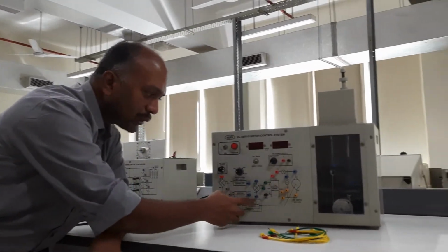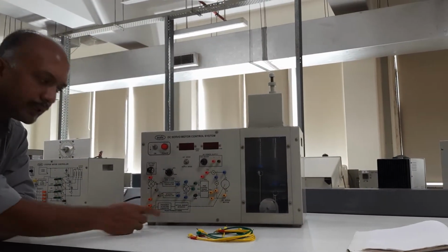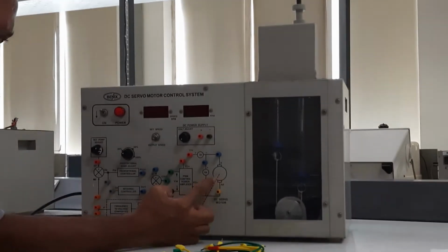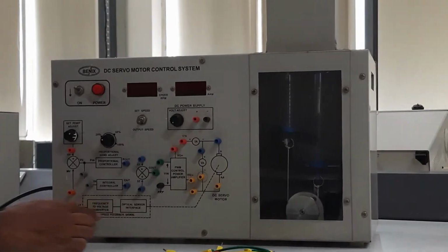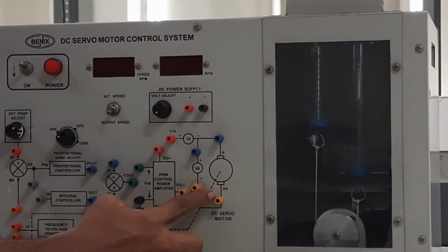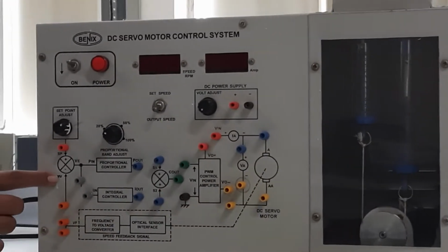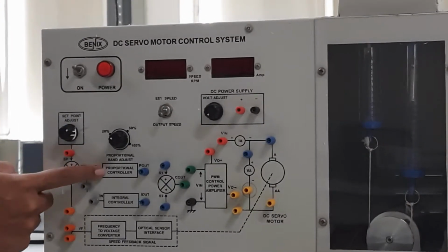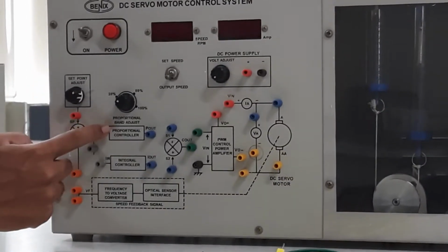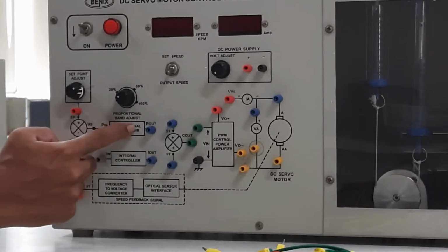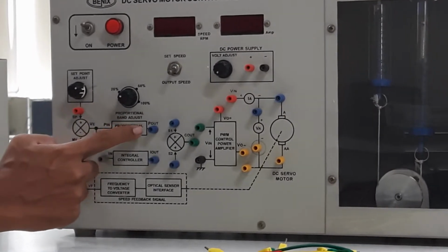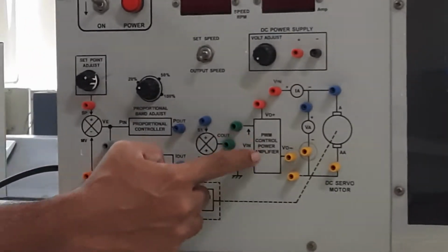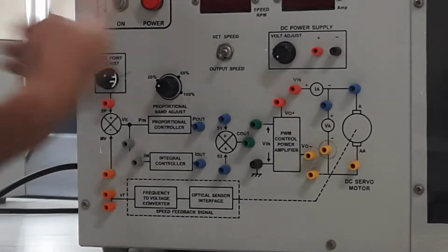So that is what you have inside this optical sensor, and the frequency to voltage converter. Based on the current speed of your motor, or the armature voltage of your motor, that will be fed back to this particular summation unit, and the error will be fed back to the proportional controller. When an error is fed back to the proportional controller, it will adjust its tunable voltage to this power amplifier, and this particular cycle keeps on repeating.